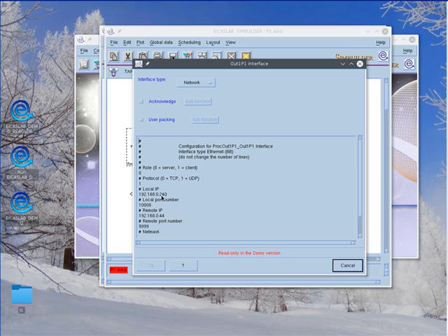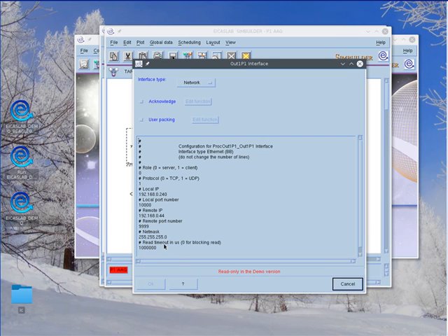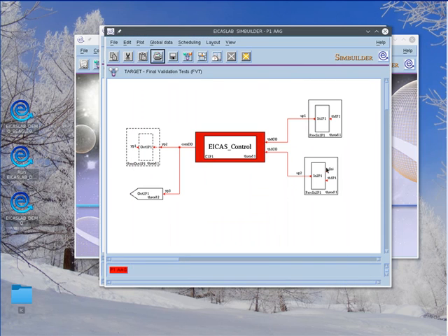The local IP is the IP of the board, and we set here the port used for sending data. We then have to select the IP and port number of the receiver, which is always the EICASLab RCP platform since the plant emulator runs on it. Then we specify the net mask and a read timeout. The two other interfaces have the same type of parameters.